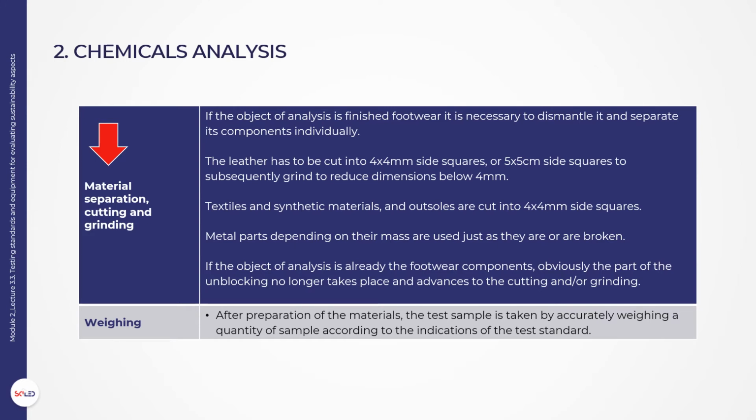If the object of analysis is already the footwear components, obviously the part of the dismantling no longer takes place and advances to the cutting and/or grinding. Weighing. After preparation of the materials, the test sample is taken by accurately weighing a quantity of sample according to the indications of the test standard.